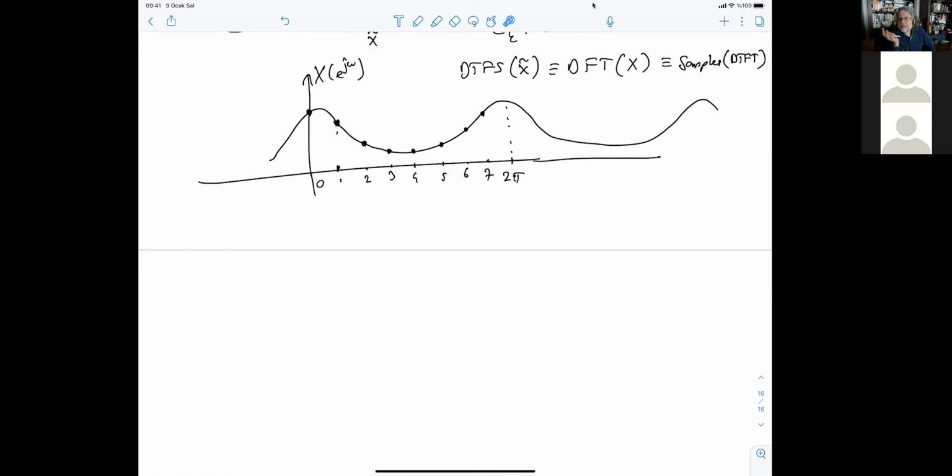I don't need them. I don't need to represent them. I can just cut, send it, and the receiver will get it. Just paste to the other side, to the right-hand side, by conjugating the values. And yeah, that's the DFT. Now I can take the inverse DFT and reconstruct my signal. That's why it's not so bad. It is complex valued, which is bad, but half of it is enough for you.